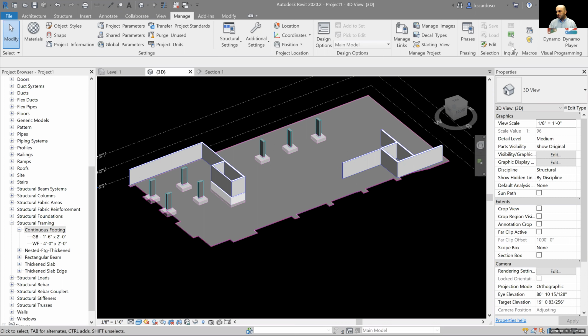Another important thing to note with warnings is that the more warnings your model has, the longer Revit takes to orbit, to work in the model. You ever heard the term, oh man, my computer's so slow? Sure, it might be your computer, but the biggest thing I ask sometimes is, how many warnings do you got? Because this is relatively a simple model, but if this were a tower, a 24-story tower, and there's a boatload of warnings, Revit has to regenerate that warning every time I orbit. Every time we click on an element that has the warning and we're just orbiting and adding more to it, Revit is regenerating and it's thinking about that. It just never stops thinking and tracking it. So try to periodically clean up and look at your warnings list. Okie dokie.